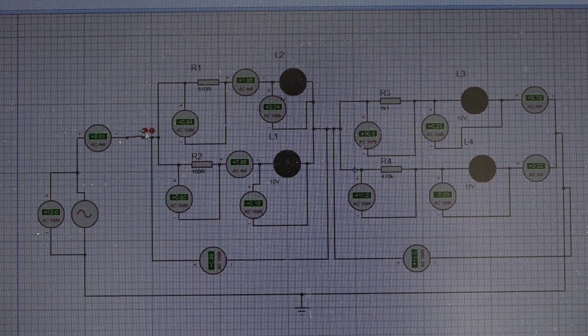Then what is the measured AC voltage at point C? Calculated it was 0.9438 or 0.94 volt. Simulated it's 0.94. Right? Then at point D we have to measure AC voltage. Calculated it was 0.7969 or simply 0.79 volt. What did they measure? Class, what is the measured value at point D?